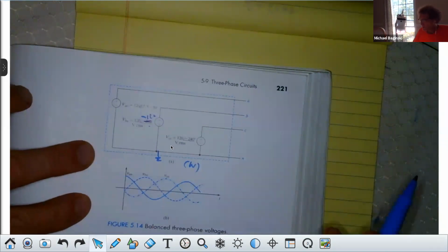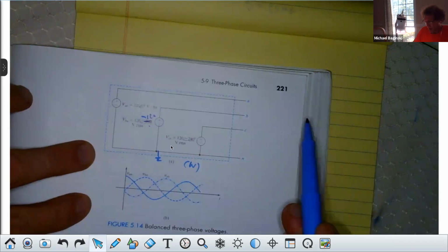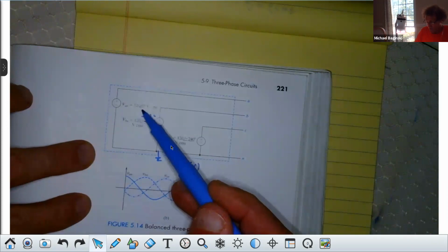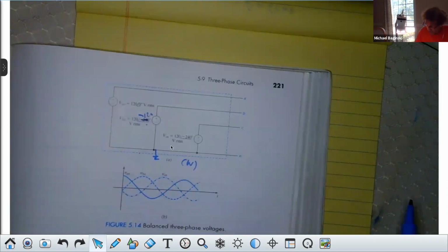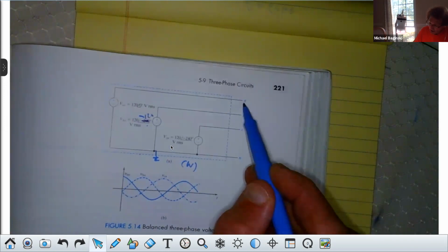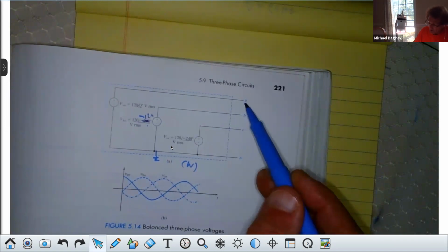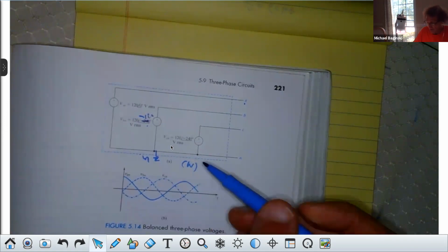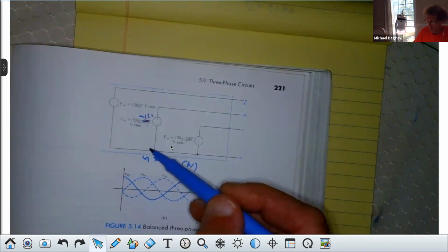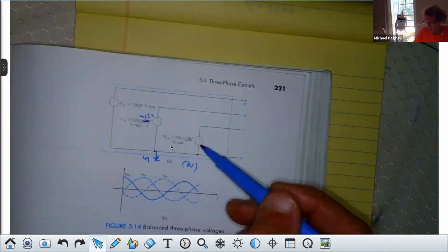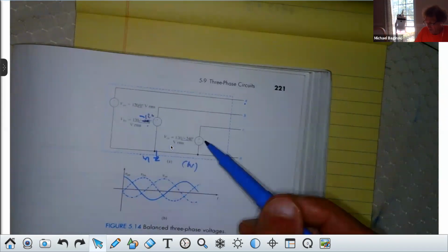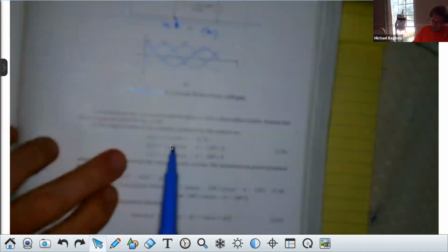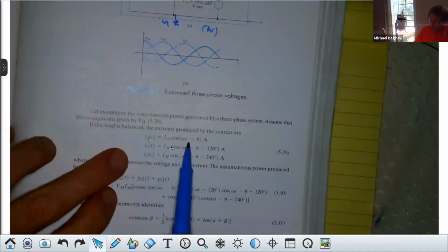And this is going to probably bore some of you, but just appreciate what I'm getting at. They are something called sequences. The first sequence, the 120 volt source at 0 degrees, is just like the voltage sources we've been using. You'll see it's small a here. That's at the transmitting end of the power. And there's a neutral here. It'll be a small n here. Don't worry about it. Then there's the next phase, 120 volts at minus 120, and then 120 at minus 240. They're exactly 120 degrees out of phase. When you go through the math on this, and here's where I end, if you take the first current, it will be Im cosine of omega t minus theta.